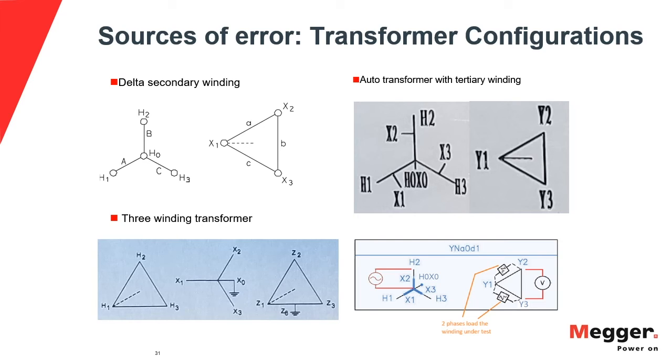Nowadays, modern TTR instruments have provisions to help the user a lot. They have the tables we discussed, and they calculate the ratio for you when you enter the nameplate values. So it's really important that we configure the unit we are using correctly.